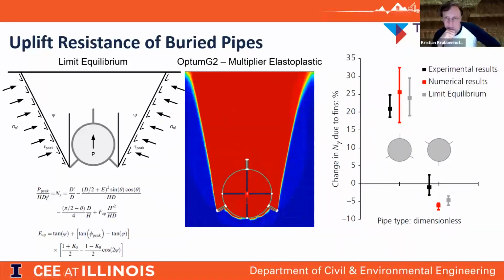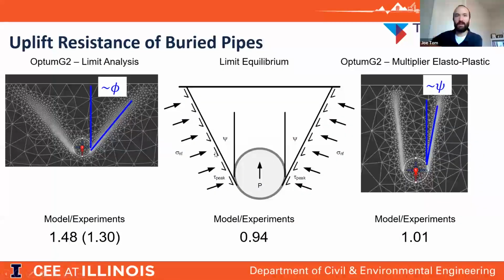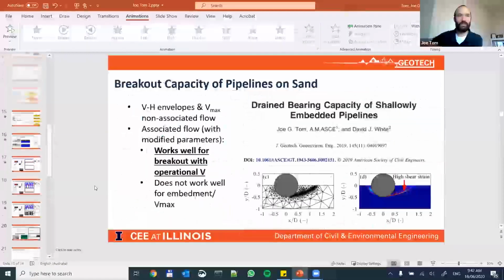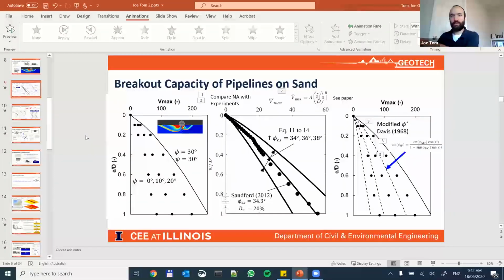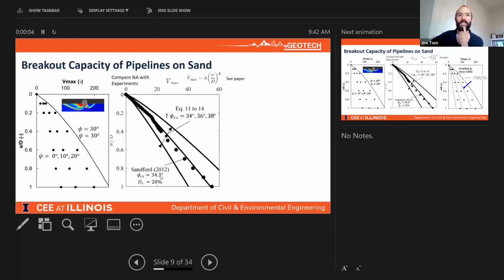Quite variable. I think there are two questions there. One is about stress level dependency. It's very important. If I jump back, there are two things that are useful to point out. If we have a look at the center figure here, we've compared versus some experiments. This is again going back to the vertical bearing capacity. The experiments had a measured relative density, and we know the friction angle of the soil. So we can then link that to what the friction and dilation angle should be for that condition. If you had a different density, you would get a different friction angle. So you need a way to understand the density and also what that means for the friction and dilation angle. In general, I have been using Bolton's equation. There are other approaches you can use to consider that stress level effect. But basically, when you go into the FEA, you just need to plug in the correct value of friction angle and dilation angle.